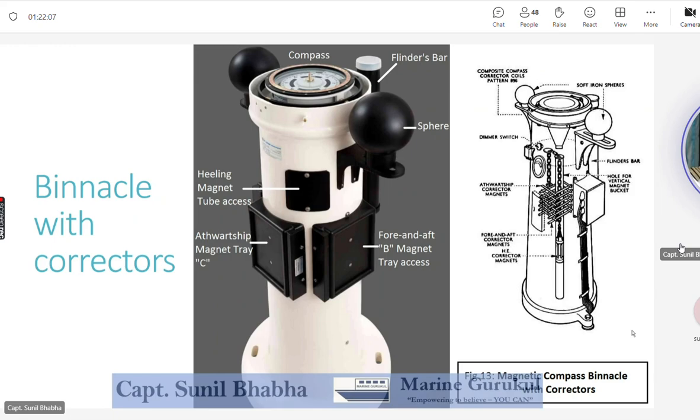Say for example, on a ship the compass adjuster checked coefficient B and it comes to 3 degrees. So he is going to place the magnets which turn the card by 3 degrees only. So he can use 1 pair, 2 pair, 3 pair as he requires. Okay, sir. Understood. So one pair means one magnet on each side, one port and one starboard, or both the magnets on port or starboard? One pair means one magnet to the starboard side of the periscope and one to the left side of the periscope. That is one pair, beta.